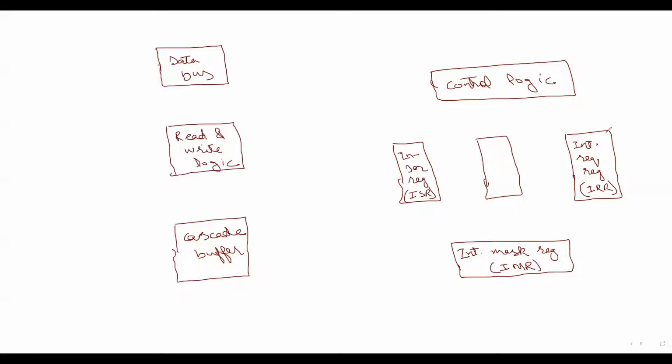Every bit represents the status of an interrupt. We know that it is able to provide 8 interrupts. So the status of these 8 interrupts is stored in these registers. And this one is the priority resolver. This is not a register, this is a resolver.